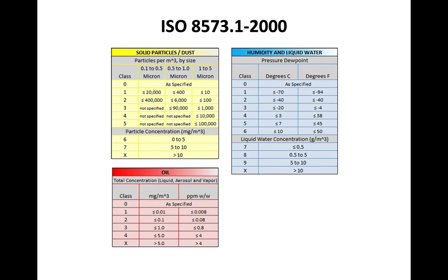For example, you need an absorption dryer, adsorption, or other technology. There is a difference between adsorption and absorption, but both kinds of technology are suitable for applications that need a pressure dew point lower than 0 degrees Celsius.